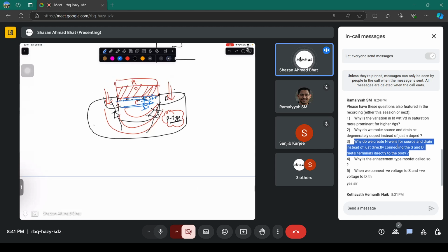The other way of thinking about it is how you make a CMOS technology, that is PMOS plus NMOS. You integrate it by connecting another structure here and making the source and drain contacts, with metal, oxide, semiconductor, and these are the contacts here. There is a buffer layer to isolate these. This is P plus, this is P plus, this is N type, and these are holes, and there are isolation layers present here.